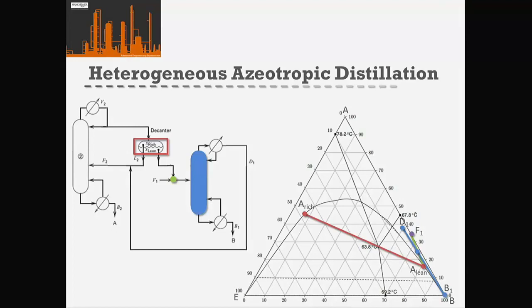So as we spoke about, we're designing our system, but we still need to think about our optimization afterwards. So if we draw this point right up to our azeotrope and we find that we need to adjust it slightly with a slightly higher concentration of A, we then move into something that's impossible. Yeah? So if we stop just short, then that allows us to adjust this point in essentially all directions rather than just one direction. Yeah?